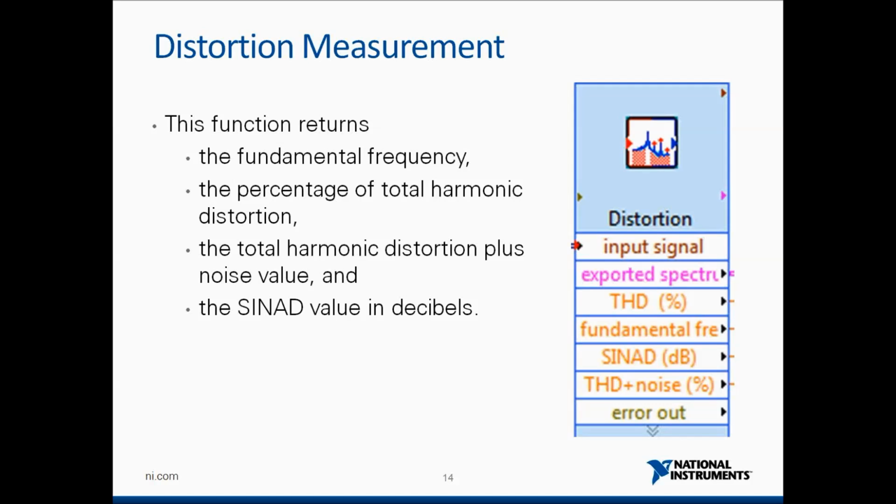Now let's look at a more complicated wave which represents signals in the real world. Say you have a square wave. If you try to do an FFT of a square wave, you will find that it consists of a lot of frequencies. A very important concept, for those familiar with an EC background and those who are not, is that any wave, any signal, can be written as a summation of sines and cosines, right?